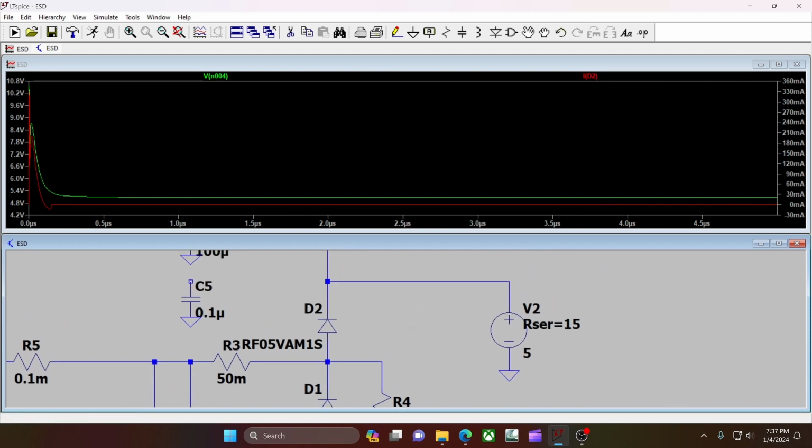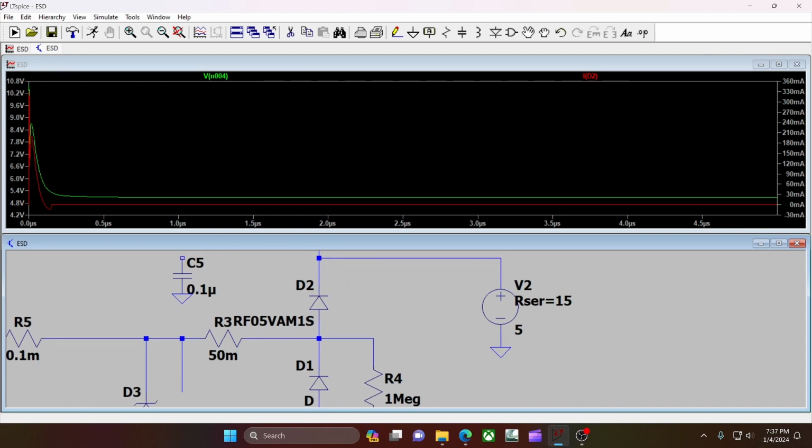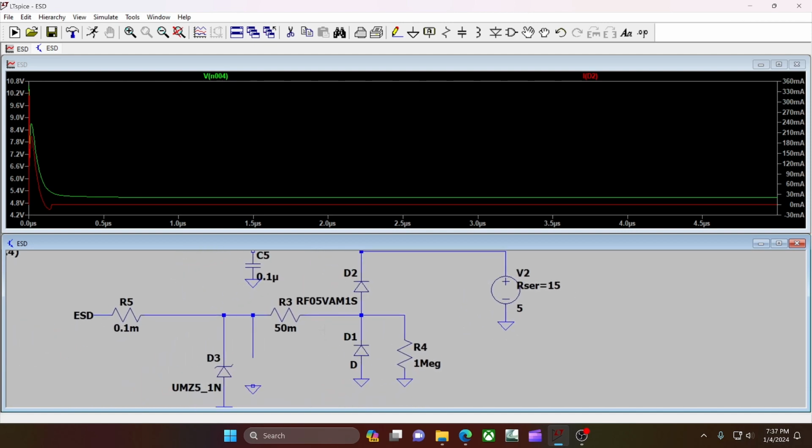I saw one thing online that said, for these brief moments, it is okay for these to take full-blown amps because this is so short. So I really tried finding something that could talk about these a little bit more other than they exist. But just couldn't do it. So this also brings to light something you see when you look at 5-volt TVS diodes. That is that their clamping voltage is typically around 9. Maybe 10, 11 if you're having a bad day.